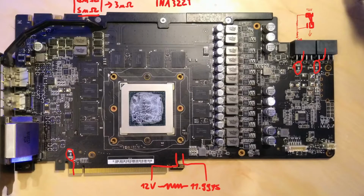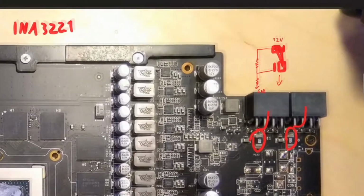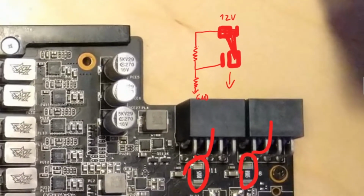So yeah. And then there's the other method that is just no compromises, power limit be gone. And that's this method basically. So what this is, this part right here is the padding below one of those shunts. So if you remove them, you will see 2 big pads and 2 small pads.